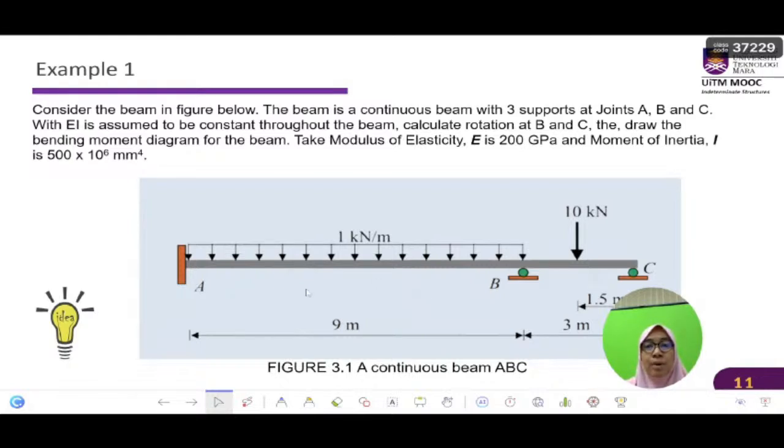However, when we analyze this using stiffness method, we have to analyze this based on stiffness matrix principle, where we have to count the degree of freedom per node. And in beam analysis, we consider two DOF per node in Y and Z direction only. We don't have to count X, because there is no horizontal force and no horizontal displacement in a beam.